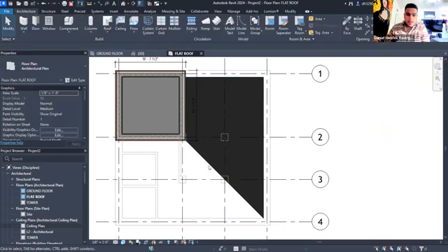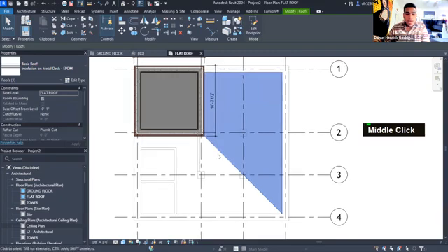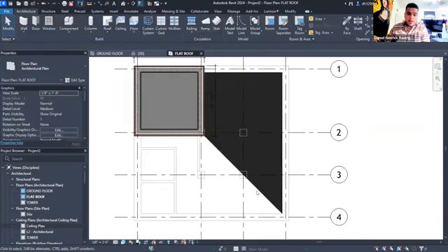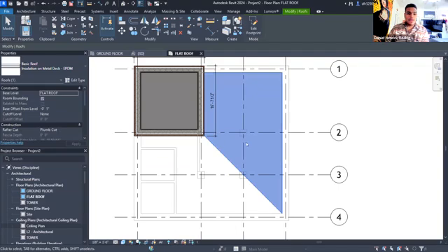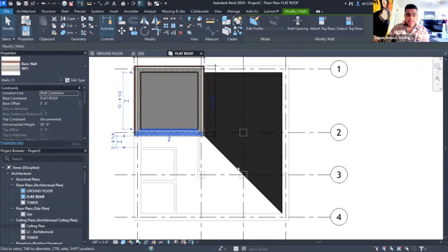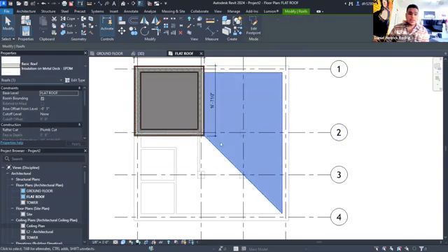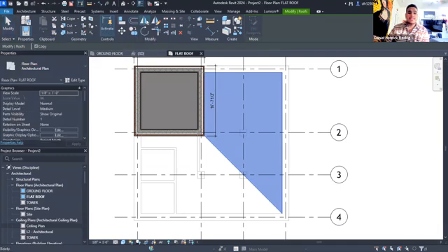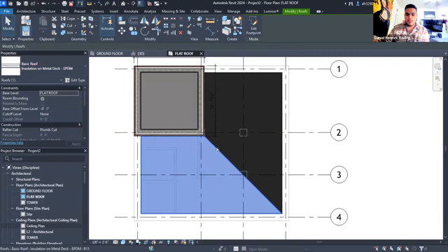Perfect. All right. Now, we have 2 options here. We either do the same thing all over again on the other side, or because they are symmetrical, we can just try to use this roof to put it there. And how we're going to do that? We're going to click on the roof, which is going to open the Modify tab. Whenever you click on anything, it's going to open the Modify tab, essentially. So you're going to click on the roof, and then we have this tool here under the Modify section called Mirror Pick Axis, right? So usually copy is going to be unselected here. Go ahead and select it. And we're going to pick this axis, and it's just going to put it down.